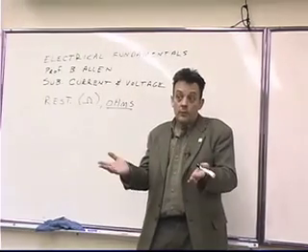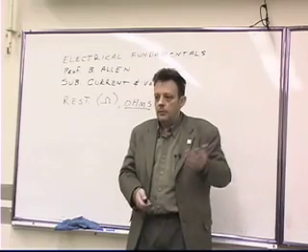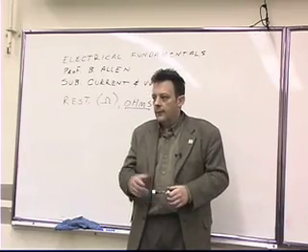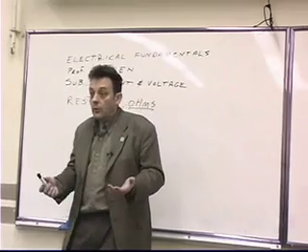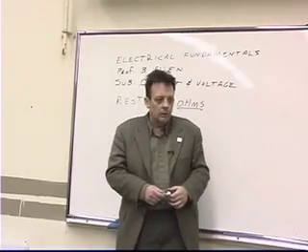Well, I may not have overloaded it. It depends. What if I have a 600 amp main? And let's say that breaker is a 60 amp breaker and that the hair dryer is only 1500 watts. I haven't overloaded it. Okay, but I've doubled it. Exactly. I've doubled the load.